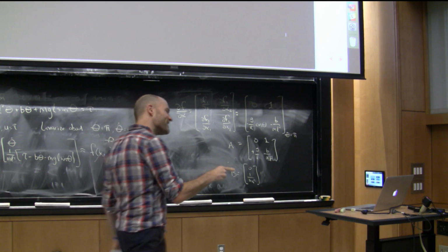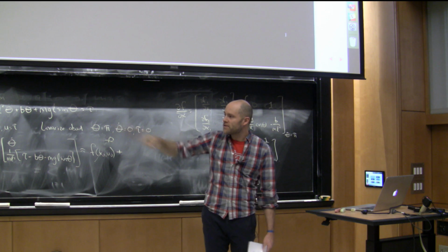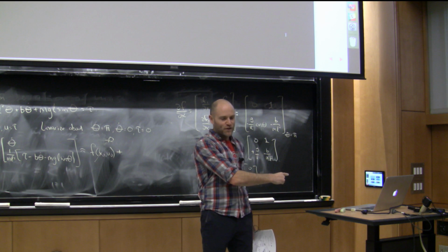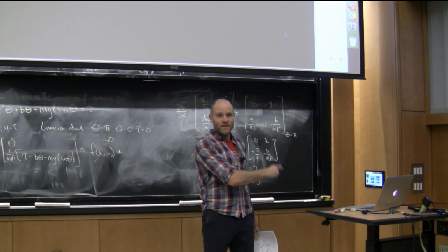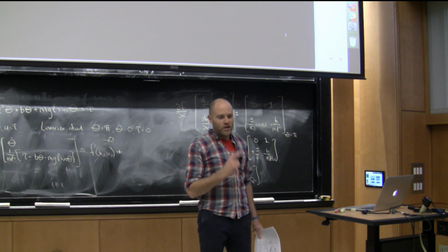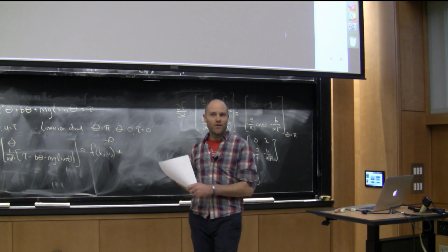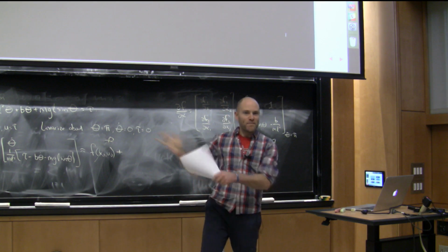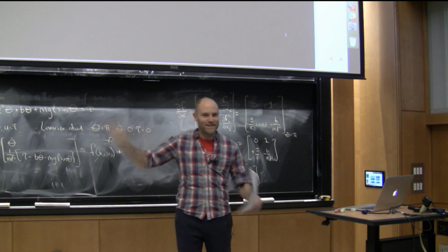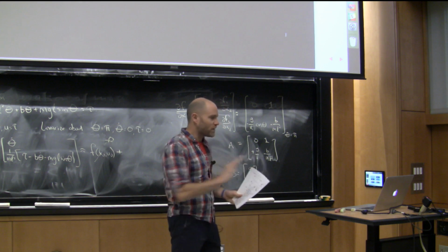So there's two things that go bad here, right? And that are subtle. They're missing here, sort of. Your LQR controller will, if you ask it for a control decision far from the upright, give you a ridiculous torque. And that may or may not be a good thing. It'll go off to infinity. The other problem is that if you don't wrap your coordinates, if you say, hey, I'm trying to stabilize pi, 0, and I'm at 3 pi, 0, and I call LQR on my linear controller, it's going to give you a ridiculously big torque that is going to take you away from the fixed point. So you got to do that too. Okay, but otherwise it basically works.